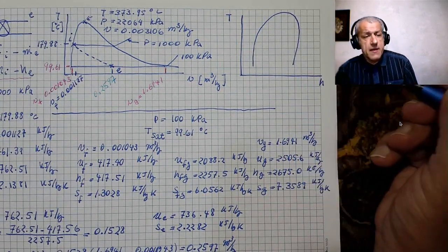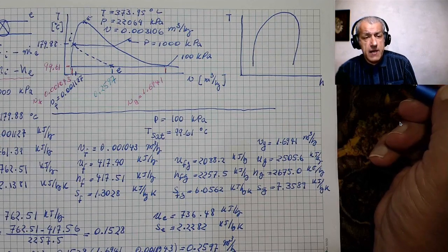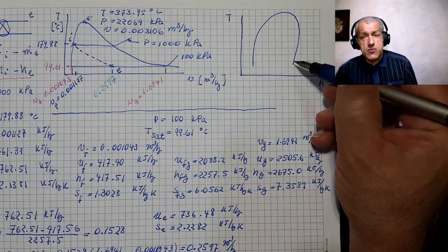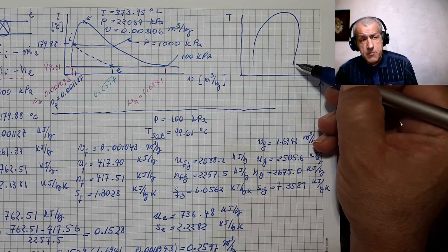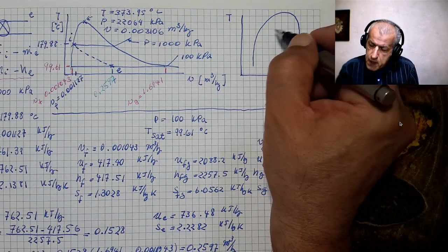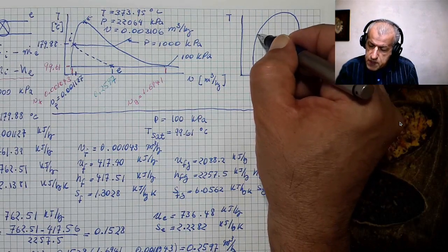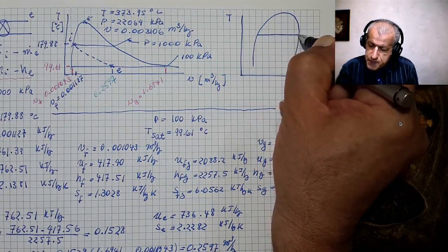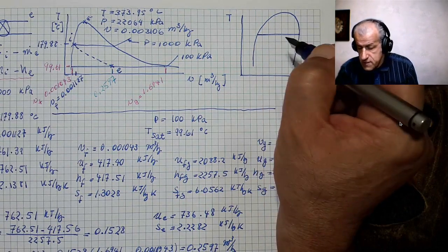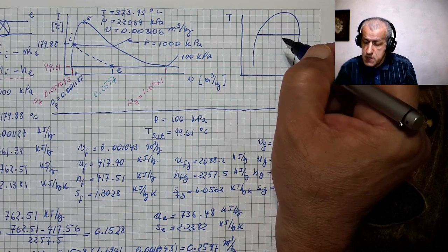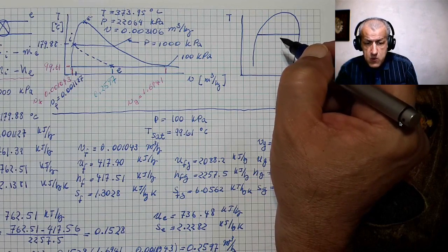In fact, in the TH diagram, the enthalpy of saturated vapor does not change very much for different pressures or temperatures. So once again we draw the constant pressure line or constant temperature line for the saturation condition.